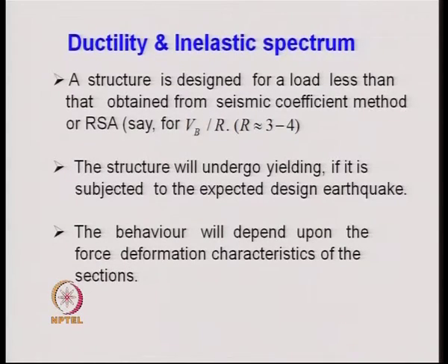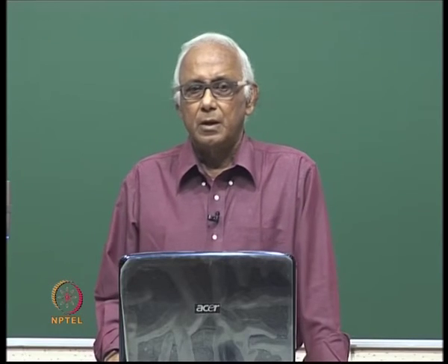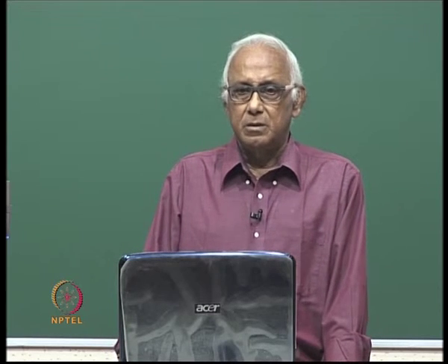Ductility for a single degree of freedom system is defined as the maximum displacement that the structure undergoes during the earthquake divided by the yield displacement. So, that is the definition of ductility, or in other words, after the yielding, how much the structure can deform is a measure of the ductility.